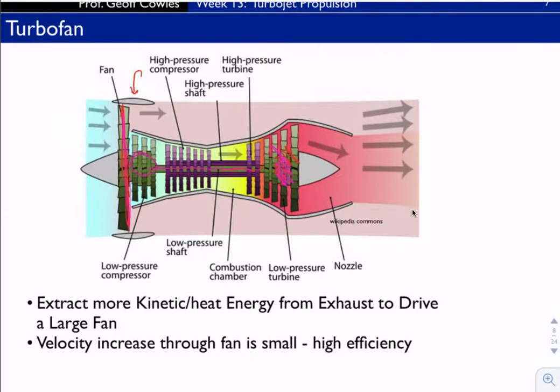And they have these purple stage of the turbine, which is the high pressure part, driving the high pressure portion of the compressor here. So it's actually concentric shafts, and you can imagine how mechanically complex that is to have these concentric shafts that really can never fail, spinning rapidly for a significant portion of each day.